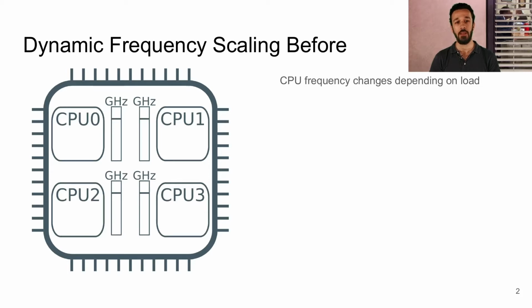One of the key characteristics of a processor is its frequency. It is directly related to performance as well as energy consumption. For more than 20 years, it has been possible to dynamically change the operating frequency of processors. This enables to save energy by lowering the frequency when the CPU is not in use. In setups where performance is key, frequency is increased when applications are running at the expense of energy consumption, while embedded setups might choose to keep the frequency low to save energy at the expense of performance.